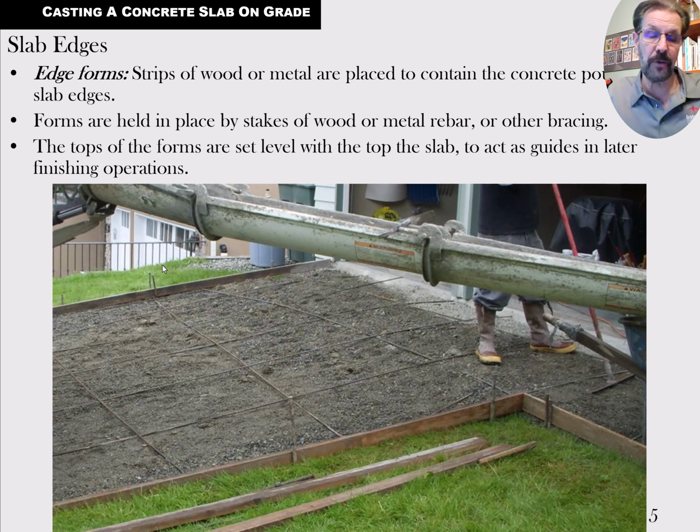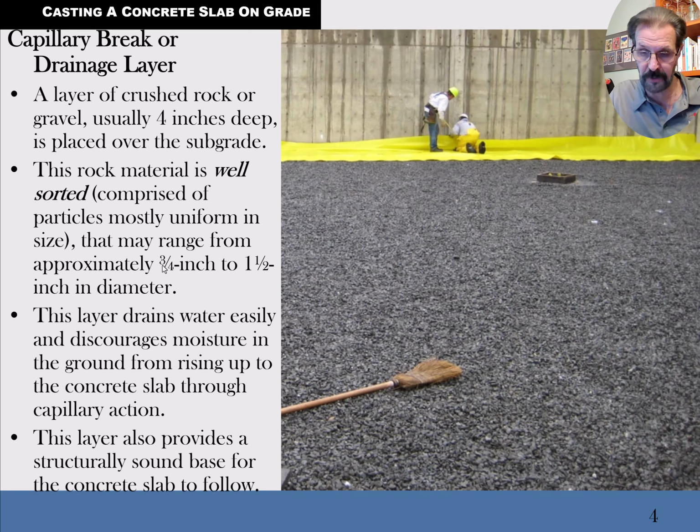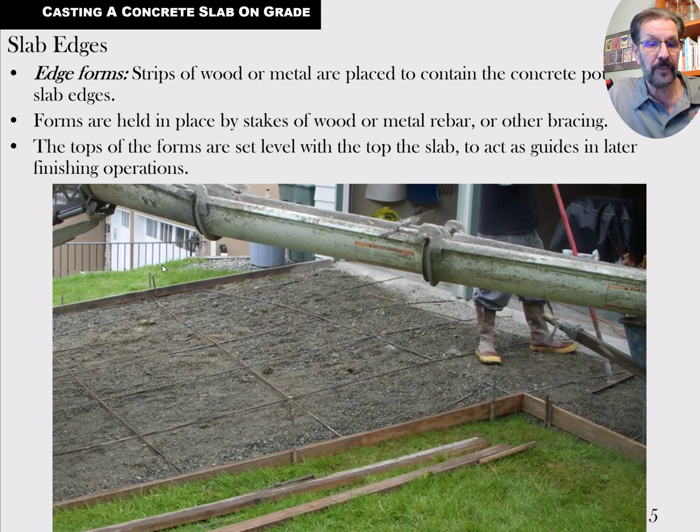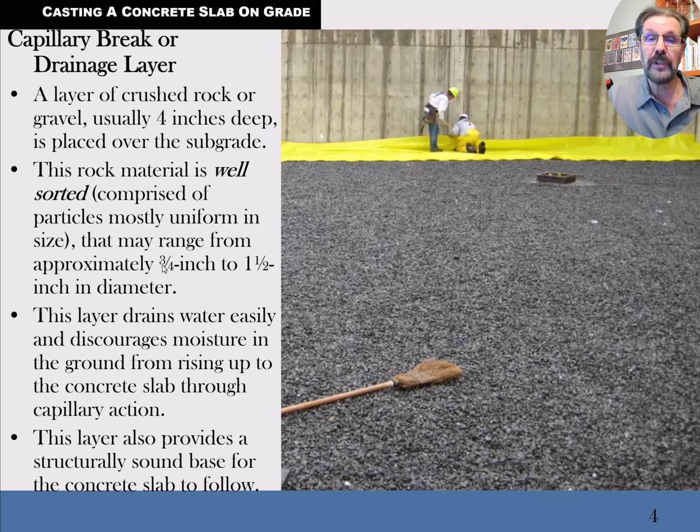So here's a slab on grade, though, that's not part of a building. The previous one is part of a building, and you need a dry slab. You don't care about a dry slab in the same way when it's a driveway. In fact, you don't mind if the water kind of migrates through it. It's not an issue. It'll dry out soon enough when the sun hits it. But so here we've got an example with edge forms, and that's the nature of driveways and sidewalks, as you end up with little edge forms, usually not even with a thickened slab at the edge, whereas a slab on grade concrete slab, like back at this picture, will typically, if it is a foundation like we have in Louisiana where it's actually supporting the walls, it'll be a thickened slab.